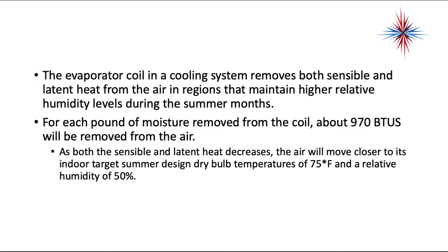Now that's tough to do in parts of the country. For example, in Florida, it's very difficult for us to hit a 50% relative humidity in the summer months inside. Okay, a lot of our cooling goes to removing moisture.